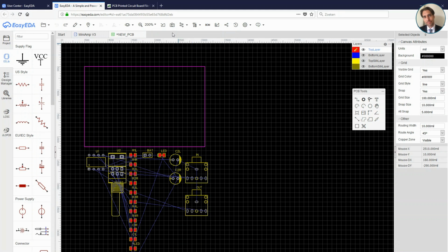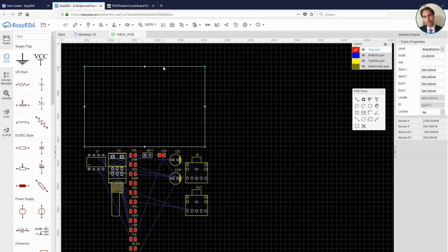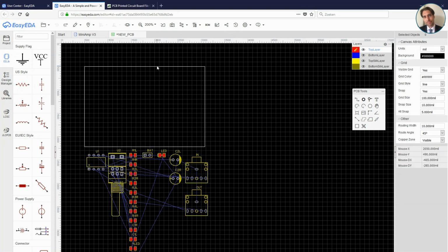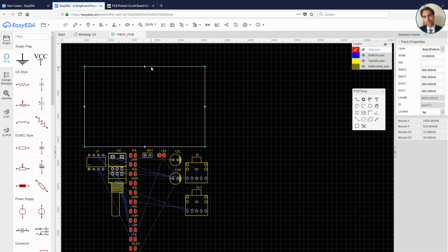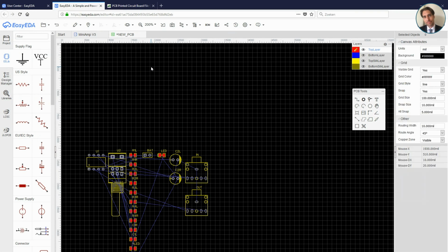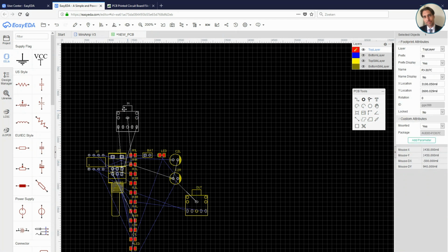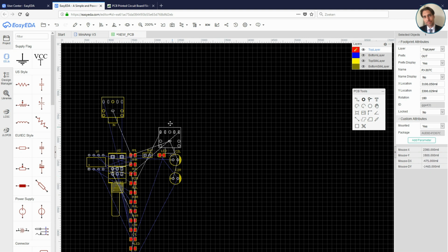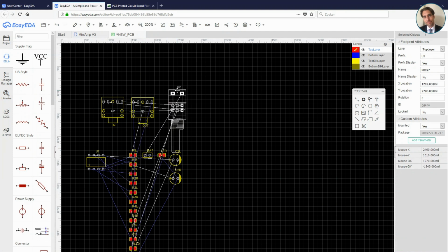And the first thing I'm going to do is delete the board outline. This is this purple layer over here at layers, and the purple line is the edge of your board. Just going to delete that. And looking at my whiteboard design, I'm going to place those components that are the biggest first and place them in roughly the place I want them to be. Again, R rotates the component. Make sure you select the whole component, not just the label, and place them in roughly the right spot.